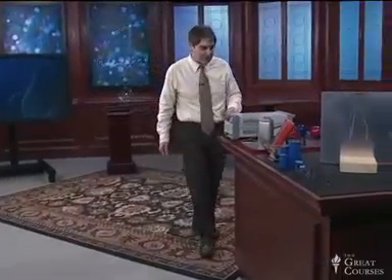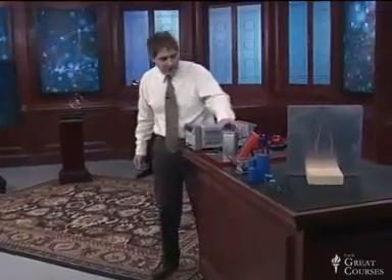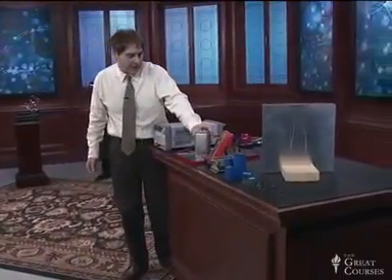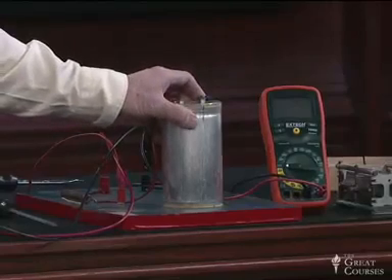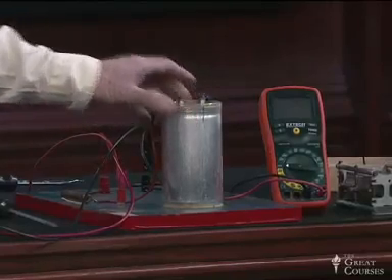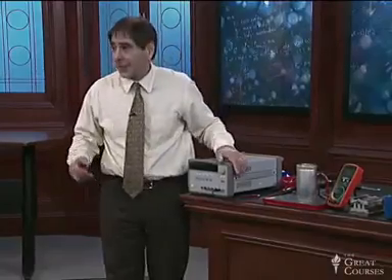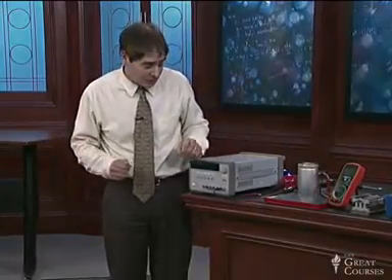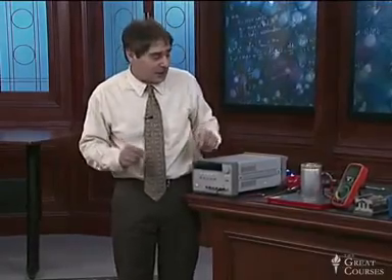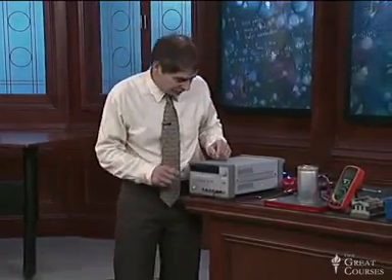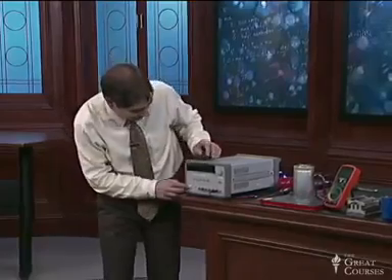I'll begin with a demonstration. Here I have a very large capacitor. It's a large electrolytic capacitor. It's rated at a maximum of 60 volts, so I've got to be a little bit careful about how much voltage I put across it. I have here a power supply that's capable of supplying 50 volts, and I'm going to set that power supply to 50 volts, and I'm going to use it to charge that capacitor. So let me begin by setting the power supply.